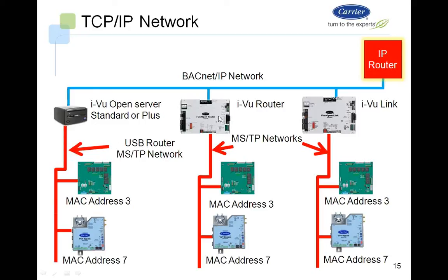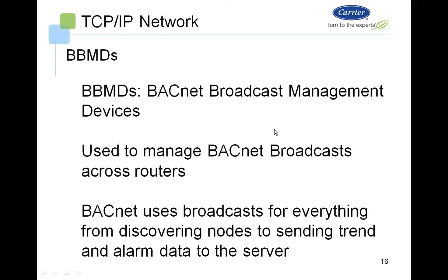When you have IP networks, you potentially need to have what are called BBMDs or BACnet broadcast management devices. In the BACnet world, a lot of communication is done via broadcasts. For example, discoveries are all done using broadcasts.